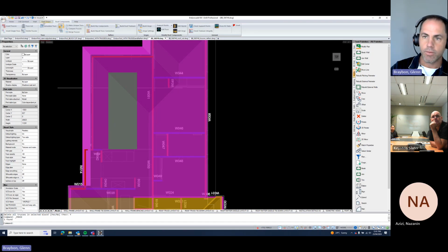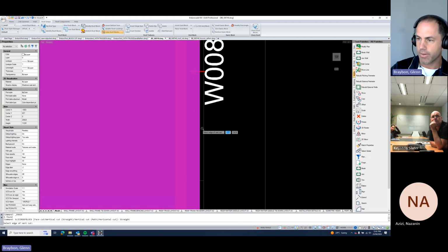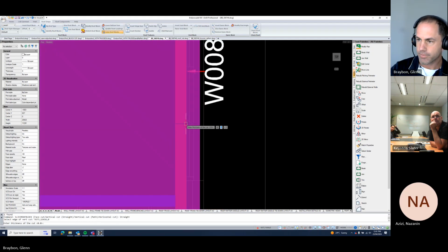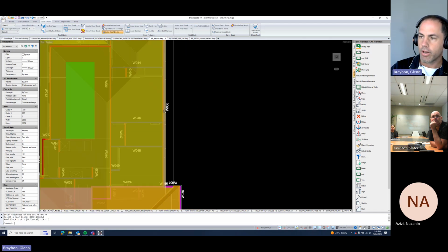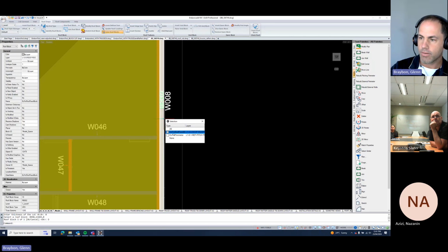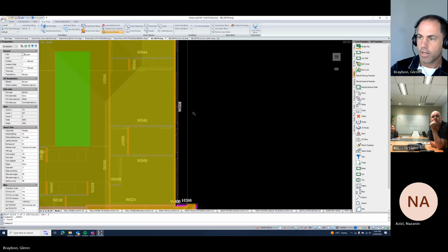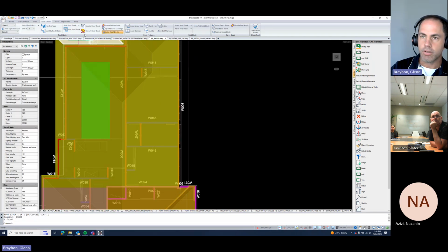So we're going to do a roof shape. We're going to cut the block. We're going to do a vertical slice on that edge. Thickness 0. Okay. Right, and then you delete that block, and then add eaves block.